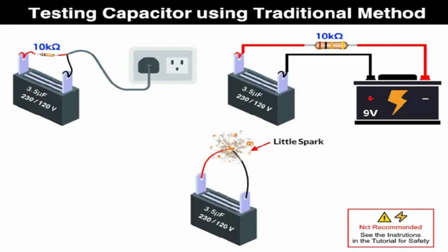Note, keep in mind that a polar capacitor should not be connected to the AC supply. On the other hand, a nonpolar capacitor can be attached to the DC supply because they are back-to-back electrolytic capacitors. As we know, capacitors block DC but let pass the AC, but still it will charge with the DC supply source until it reaches the terminal voltage level. In short, nonpolar capacitors can be operated on both AC and DC supplies, while polar capacitors only operate on DC. For more details, check the previous important post on what happens if we connect a polar capacitor the wrong way.